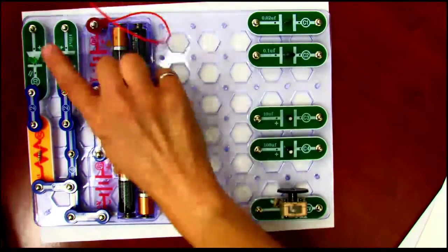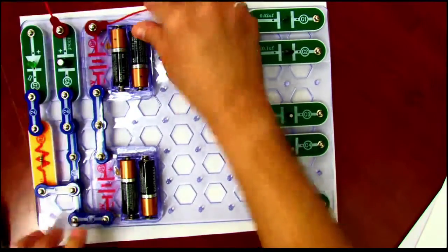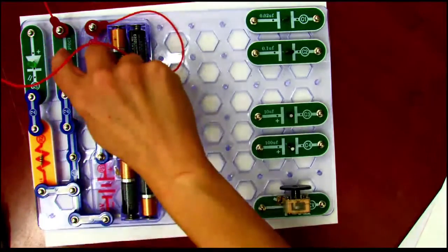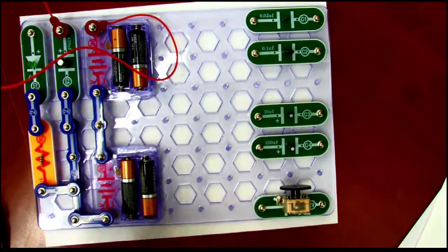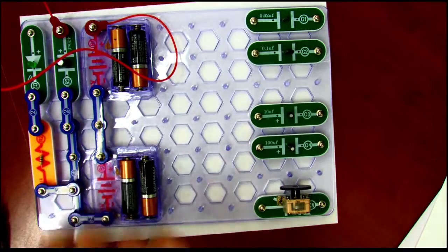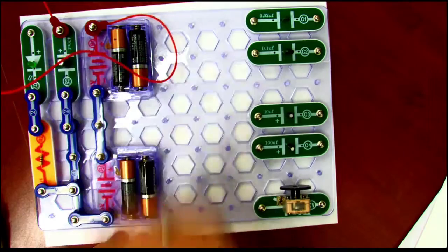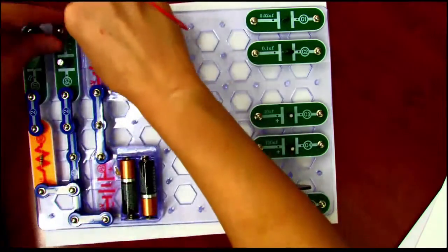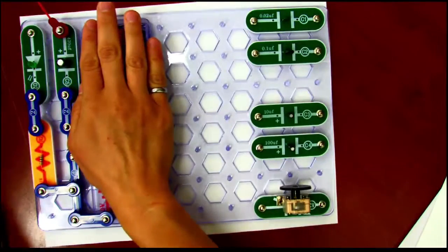If I take my discharge capacitor and connect him to the batteries for a little while, I can build up a charge in him. He has this little spiral of, I think it's paper in there, separated by oil. The paper in the oil is the dielectric, and there's some sort of metal coil in there that it's held across, and you're building up capacitance in him. And when he has enough charge, I can disconnect it from the battery, so the battery is completely out of the circuit.